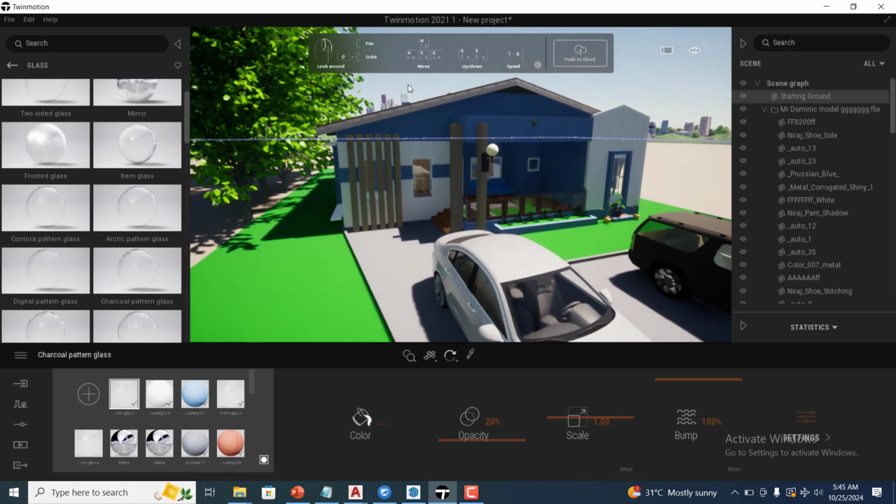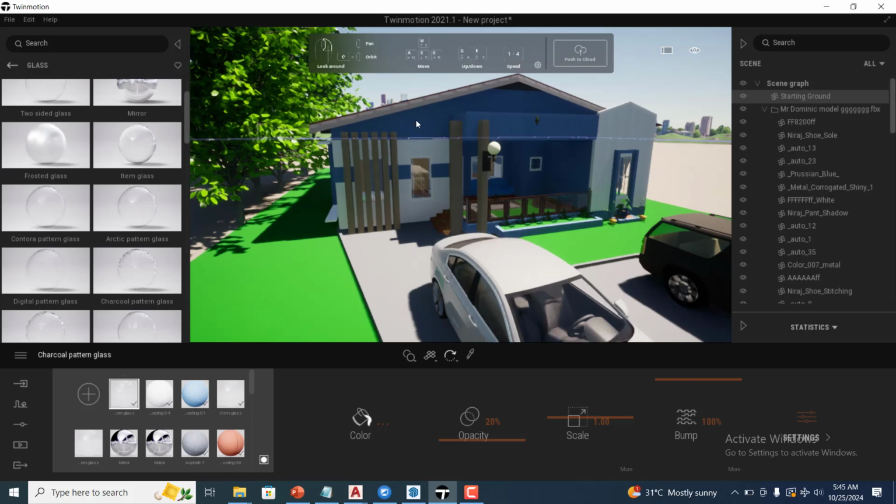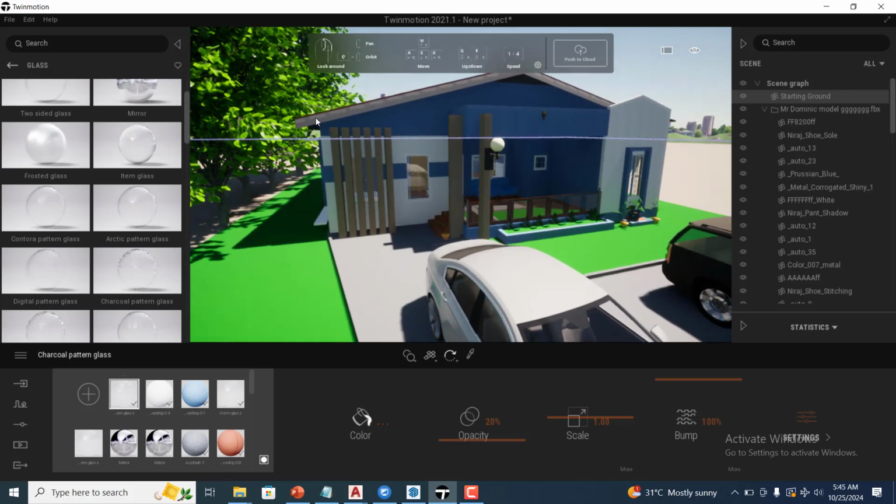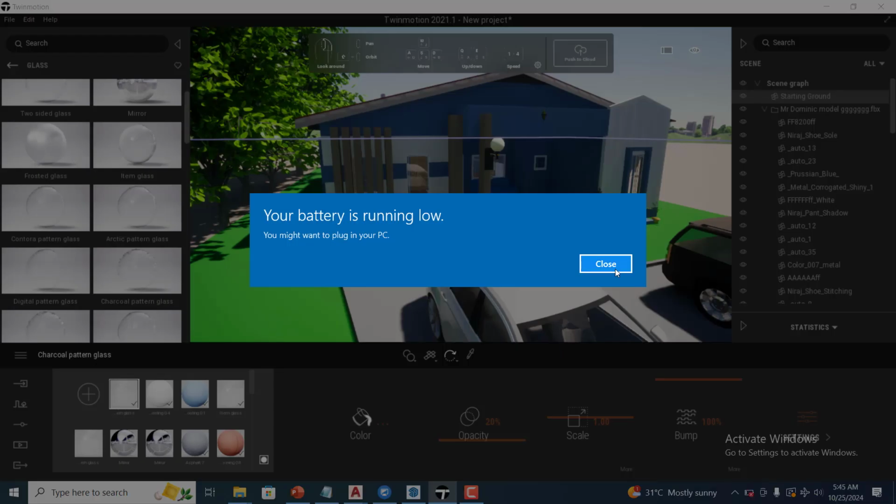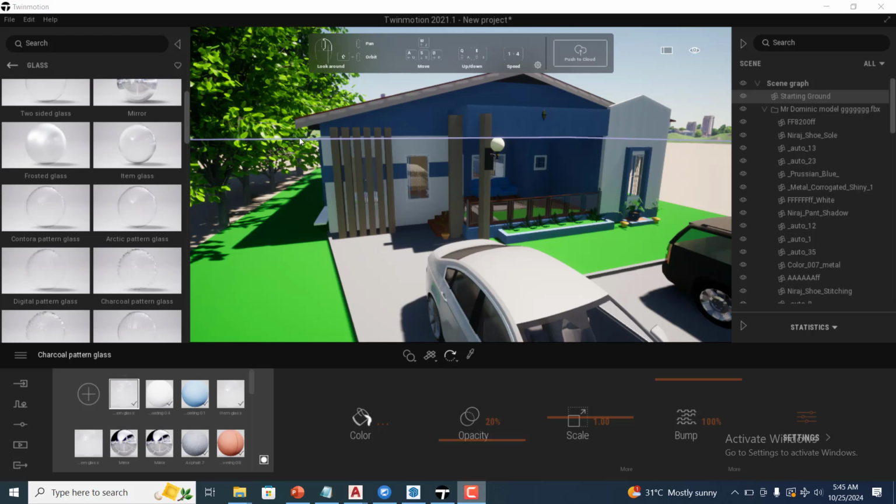So mind you, like I said, you must be very careful with your model. Make sure the materials you are applying, you don't have a similar material. You can see this ground here has a similar material with the fascia here, which is not supposed to be so, but it's from the model itself when I imported it. So that is where that challenge is coming from. Although you can actually change that and restrict the material to be applied here alone.